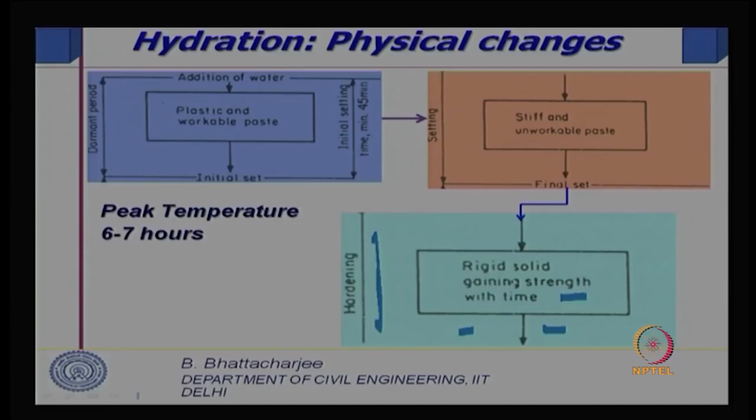Well, the peak of temperature occurs 6 to 7 hours after mixing the water, and final set generally corresponds to about 10 hours or so, not more than 10 hours, that most of the codes will specify.